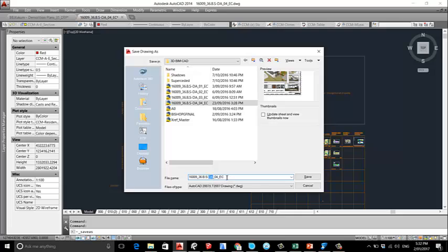It is important to put the version before the name because it is not that relevant that things organize alphabetically by the person who drew, but it's actually more important that they organize chronologically by version. If we put the person before, it will organize EC before, for example, MGP, which is my name, but it might be versions 1, 7, 17, and then my versions are 2, 16, and that is not desirable.